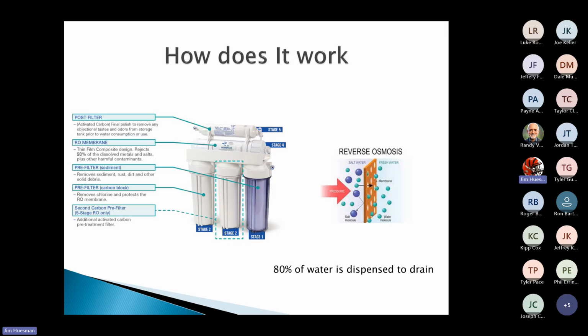So any sort of tubing that you're running RO water through, make sure it's poly tubing. Make sure that there's no metal. That means no brass as well. You can't use brass fittings on that one. So you want to make sure that we're running it and everything's going poly through it. Even the faucet that you're buying with it, it's a polyline spout, okay? That water cannot touch or really be around the metal because it will start leaking.